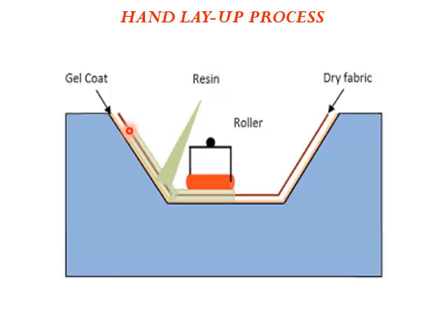Once this process is done, we take a roller and roll it uniformly over this sandwich, which is a combination of resin and fiber, to make sure there will be a compacting or squeezing action. Excess resin will come out, and there will be proper bonding between the fiber and the resin.